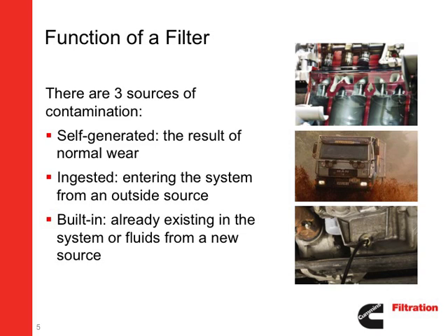The third type is the contamination that already exists in a system or in the fluids added to that system. When the oil is changed, for example, the new oil could contain a low level of contaminants. This is termed built-in contamination.